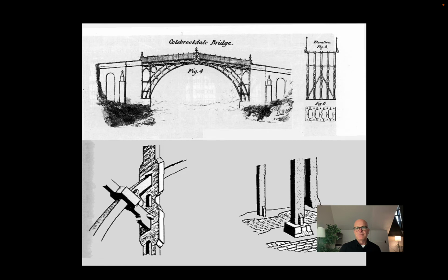And the leading iron project of the mid 18th century was, of course, Coalbrookdale Bridge, this prefabricated cast iron structure that was built in the coal and iron district of Great Britain. And we talked a little bit about how it reverted to the semicircular arch, which by this point it's known that that's not the perfect shape, but it is a shape that lends itself to repetitive fabrication because you can make the arches of the bridge from a single mold that's set to a single radius, or in this case, 3 radii that each would have a different mold.